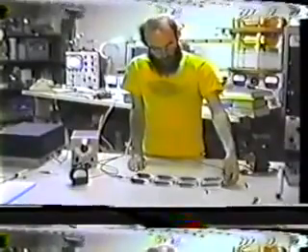And we also can use our fingers too, which serve as very good measuring devices. The voltages are low enough and the frequencies are high enough. Find the coils at the end here getting quite hot, which can be expected. And then they cool right off until the end, no heat is felt. The capacitors down here are cool. And as we get further down the line, we find the capacitors get warmer. So we find that we have a separation of the heating effect, where the dielectric heating effect, understandably, is occurring where the dielectric energy intensity is maximum, and the magnetic heating effect is maximum at the end where the magnetism is most intense.